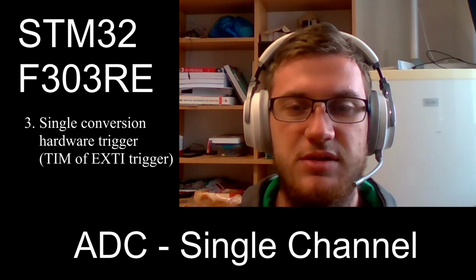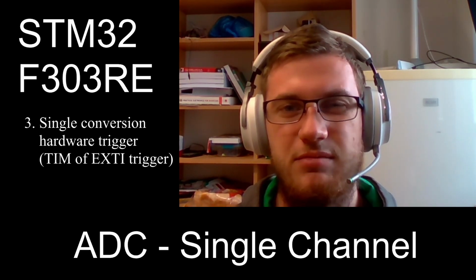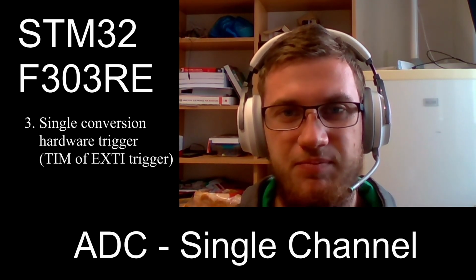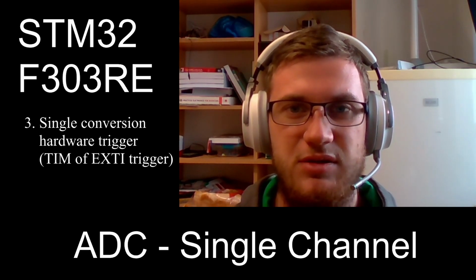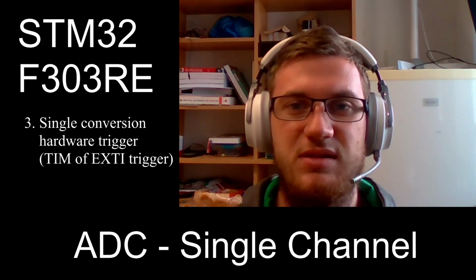The third method is single conversion and a hardware trigger. This is quite a more difficult method to set up, but it is very rewarding. You have to use a peripheral, for example a timer or an external interrupt, to start the ADC conversion. By using the interrupts, you can save a lot of clock cycles and memory.